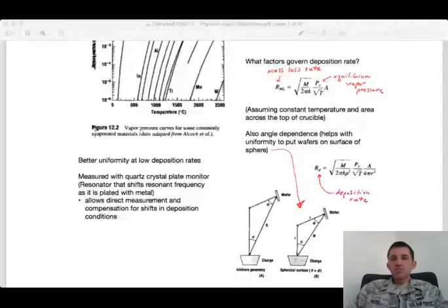But if you have a denser film, right, then you're going to have a slower buildup of thickness, because those atoms are being packed in more densely. You have a faster deposition rate if you have a higher vapor pressure because you're getting more atoms in the same amount of time. You have the same vapor pressure to temperature ratio in here. The area that you have exposed to the charge, well, no, I'm trying to think. Is that what A is? I guess it's the same A. Right, if you have a larger charge, you're going to build up faster.